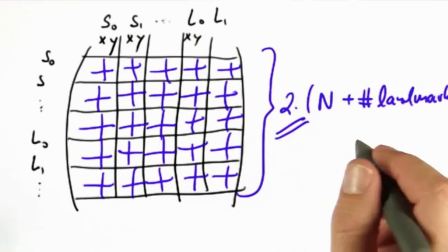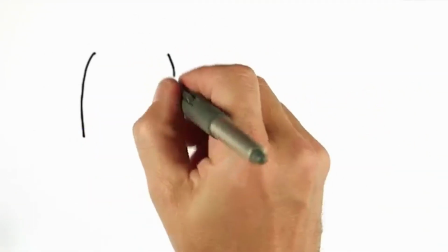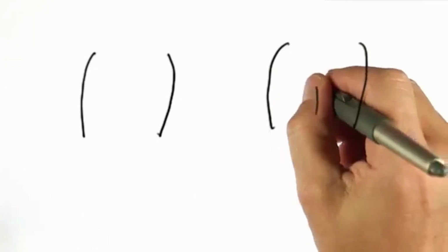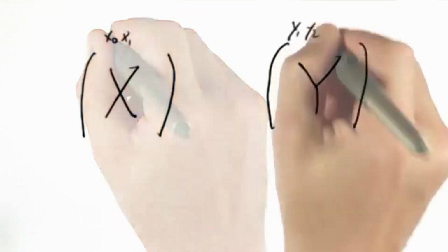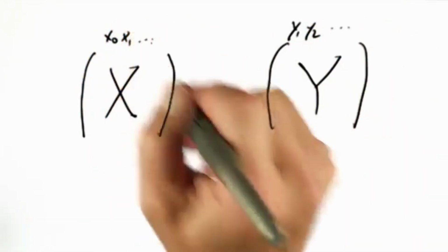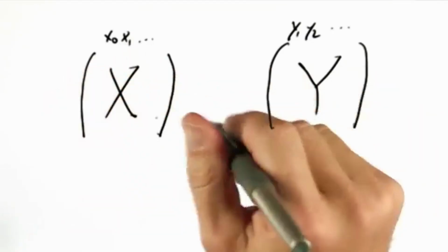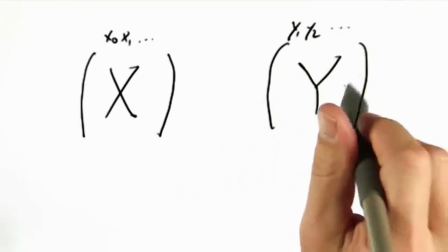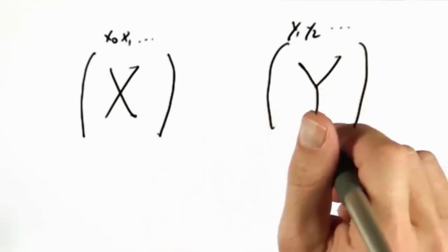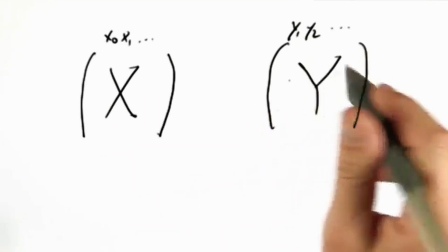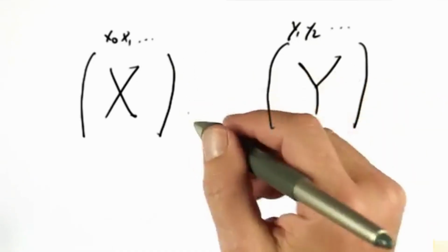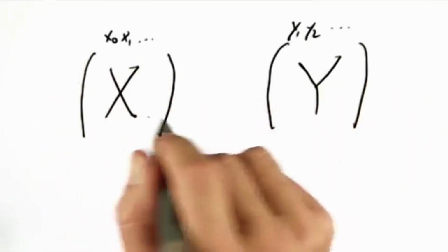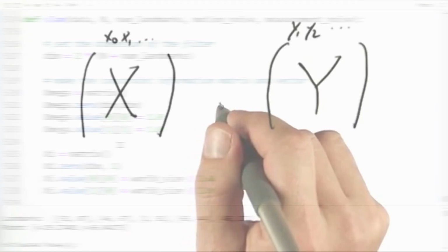You might have done this differently. You might have said, I'm going to build one matrix for x and one matrix for y. And then each of those becomes just a single value, which is closer to the way we discussed it in class. That's fine in this case. In general, it has disadvantages in that it cannot correlate x and y's. So for a real robot that has real rotations, this doesn't work. My solution is better, but for this specific example, this would have been perfectly fine.